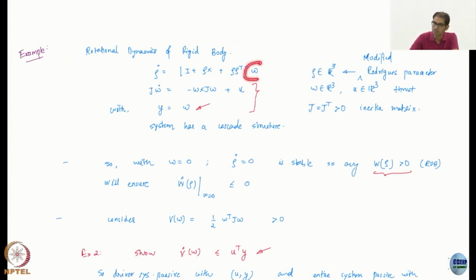There is a relationship between body angular velocity and the rate of the orientation variable. The variable is complicated and nonlinear because, if you remember, rotation is represented as a matrix and this is just a parameterization. So it is complicated, but still it is a rotation variable. Anything that gives you rotation rates as a relation with the body rates is kinematics because it is relating position derivatives.